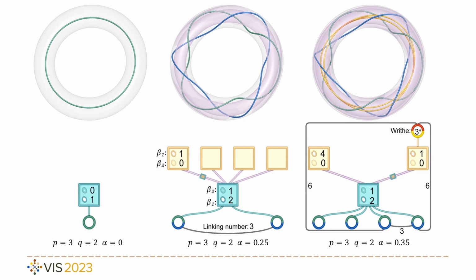However, when the boundary conditions become anisotropic, yet rotational symmetric and periodic, we observe a threefold symmetry in the contractile regions and the linking number of 3 between the two degenerate loops. Both match the threefold rotational symmetry in the boundary loads. In addition, the core of the O-ring has switched from extension dominant to being compression dominant, highlighting the increased load strength on the boundary.